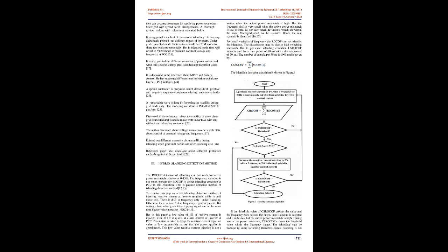The islanding detection becomes easy if there is a mismatch between generation and load. But if there is no difference between supply and demand during islanding, the passive methods do not detect the islanding phenomena and hence NDZ occurs. At this juncture, an active islanding detection technique to identify the islanding condition and to isolate the microgrid is a must. This way, microgrid stability and safety are ensured.